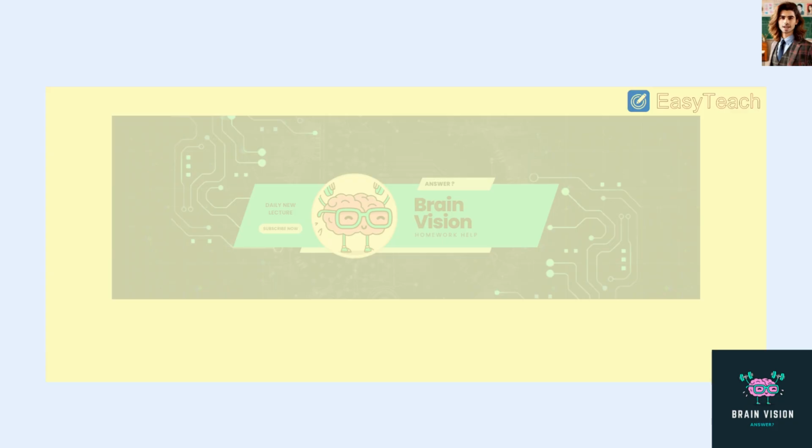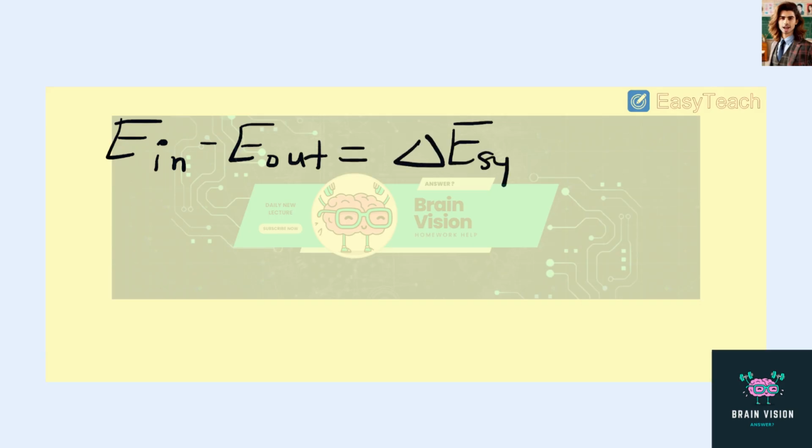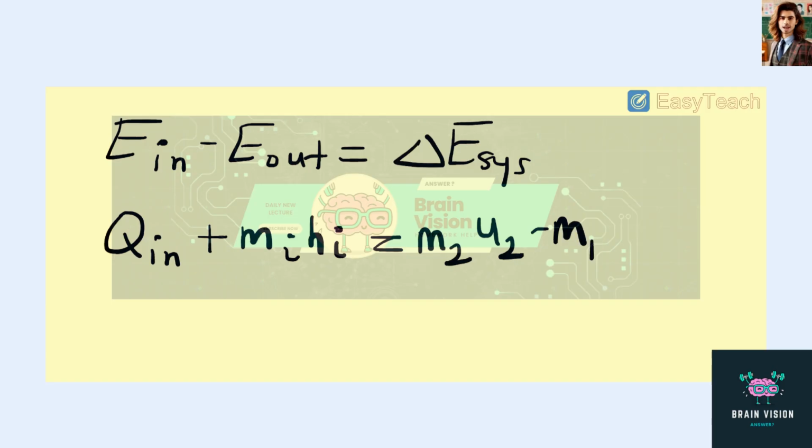Next, we're going to do an energy balance and say that energy coming in minus the energy coming out is equal to the change in energy of the system. Now, we have heat transfer, which we're going to assume is positive coming in. We also have mass coming in as well, so that's going to increase our energy by the specific enthalpy, mi hi. There is no energy leaving, so E out is going to be 0. And that's equal to our change in system energy, which is m2 u2 minus m1 u1.